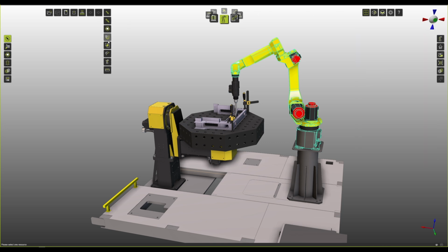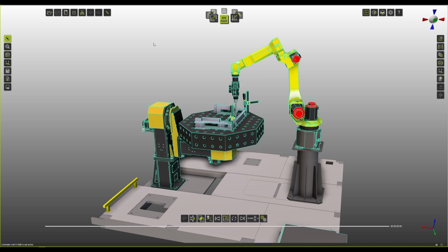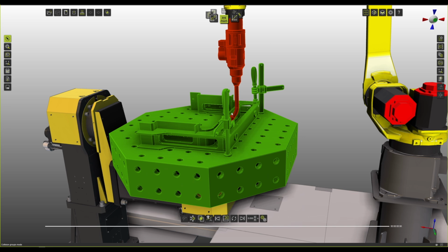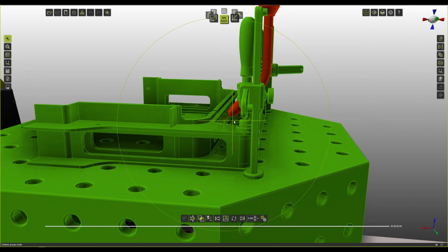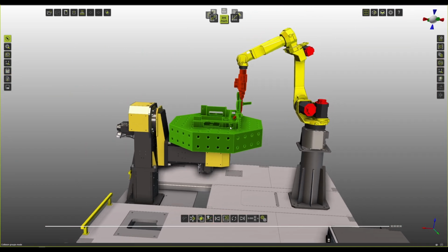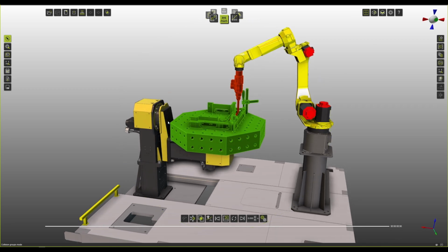As I said before, you also need the proper collision groups. So you can have collision groups connected within your torch and maybe discard anything that is not completely relevant for the process, because as I said before, this whole thing is evaluated. So if you are only taking care of the robot, the workpiece and the torch without other stuff, it will make the calculation a little bit quicker. And you can also exclude the tip of the wire because that one shouldn't be taken into account for the collision detection.